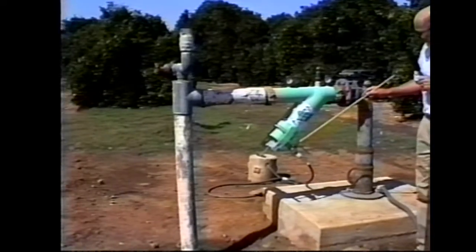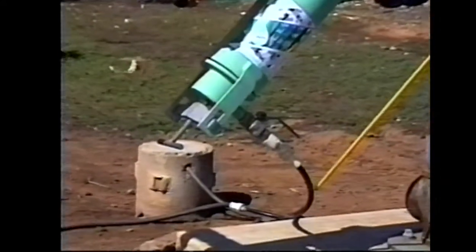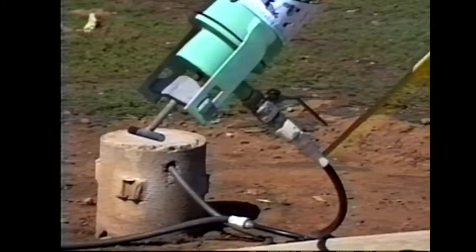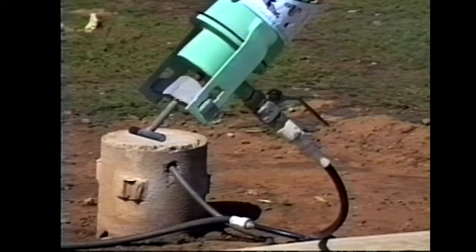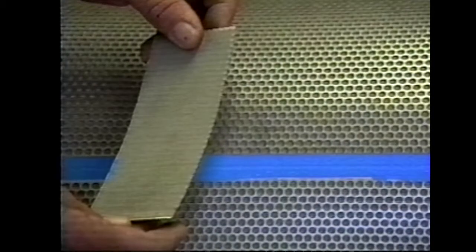The spinning motion by the water pushes the debris to the bottom of the tube, where a valve allows several gallons per minute to continually drain water and dirt to the atmosphere. These designs with internal screens and water jets should not be used if the sand is very hard and angular, as the fine inside mesh screen material can be destroyed by the abrasive action of such sand.